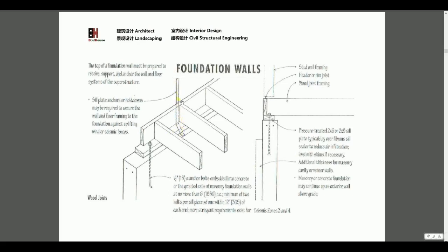On the sill plates we need to put some hold downs. The hold down function is very important. The function is to hold down against lifting force. When wind or seismic events happen, there's some lifting force, so the hold down is very important to resist it. There's another bolt, so they have the bolt to anchor to the foundation wall.